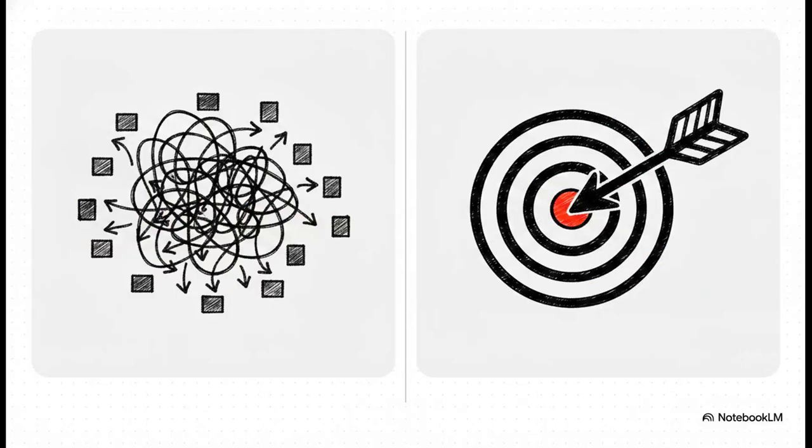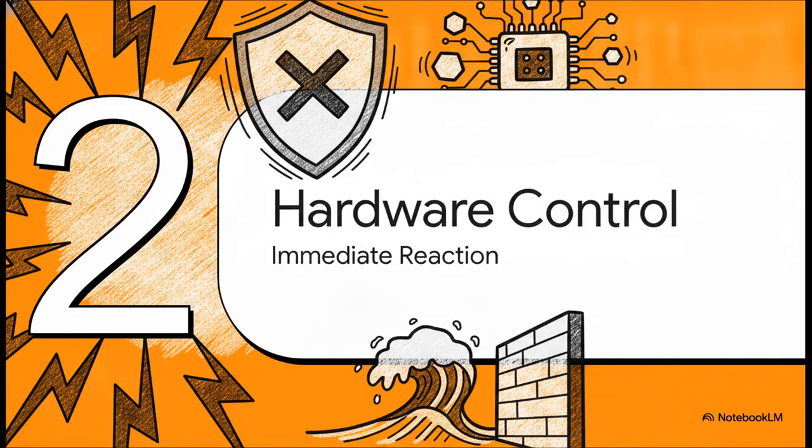To handle this sudden halt, the processor has to figure out exactly where to go next. Now, while interrupts can use a massive dispatch table in what's known as vectored mode, synchronous exceptions act a bit differently. They always immediately redirect the program counter to the base address in direct mode. This entirely eliminates the need for a large software dispatch table, forcing a rapid, highly predictable jump to a single entry point. That brings us to part 2, hardware takes control, the immediate reaction.